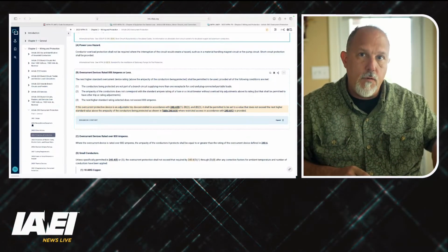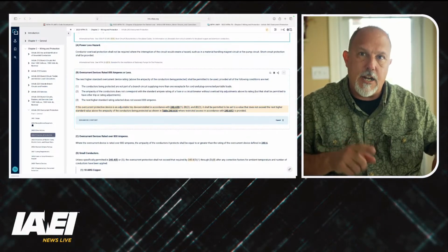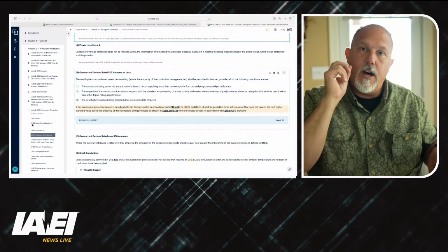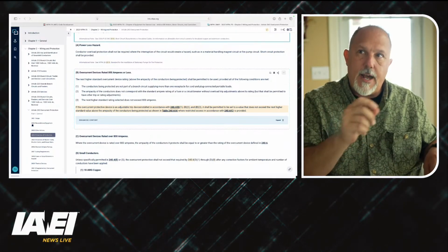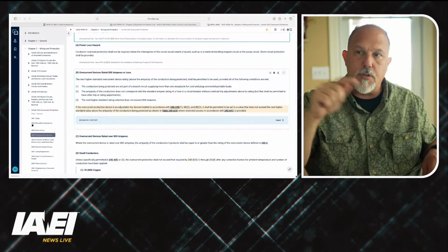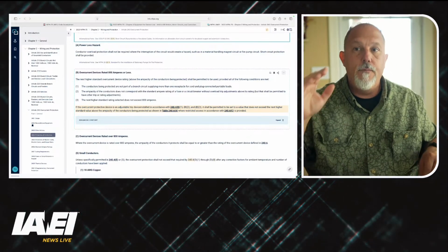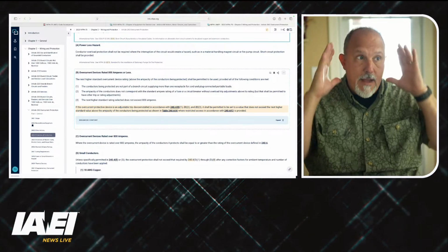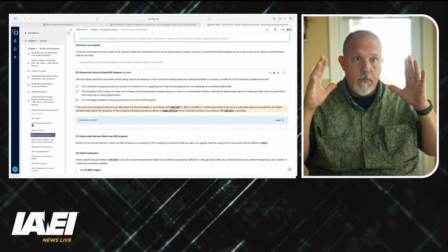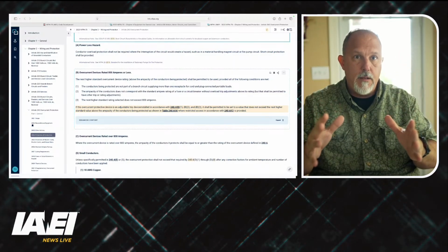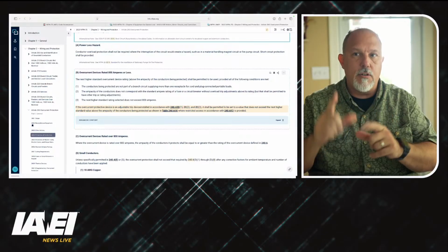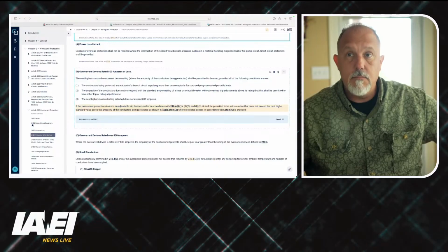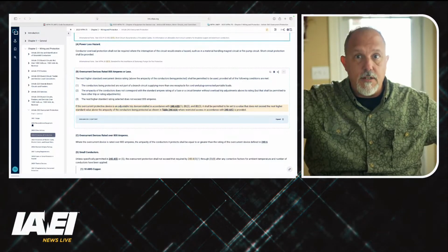As long as my overload protection does not exceed 125%, or doesn't exceed the ampacity of the conductor, then I could consider the conductor protected based upon 240.4. That's where my head's at. Because there's nothing in 430 that says I don't have to adhere to 240.4. I could go to the next larger size, meaning the next larger overload protection.